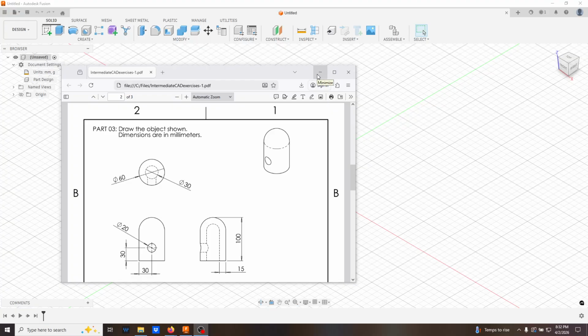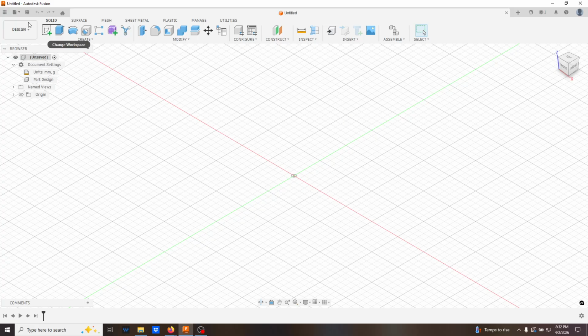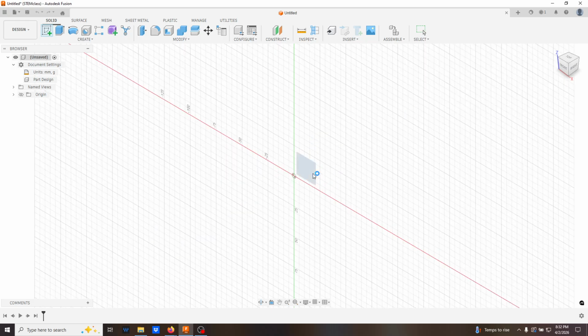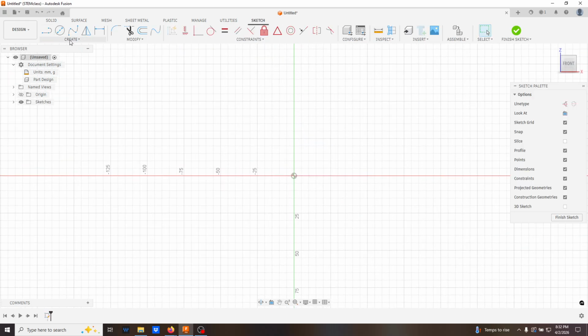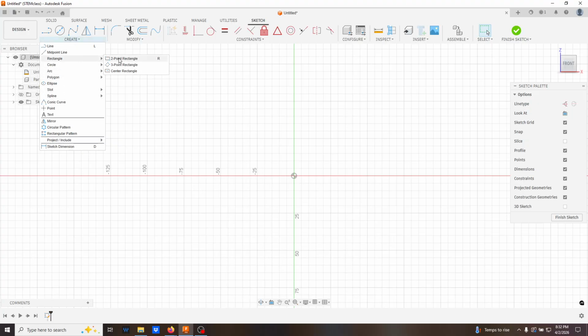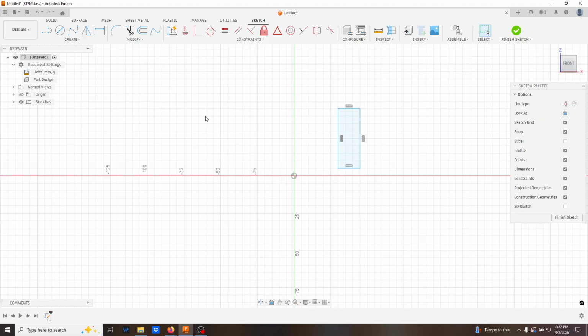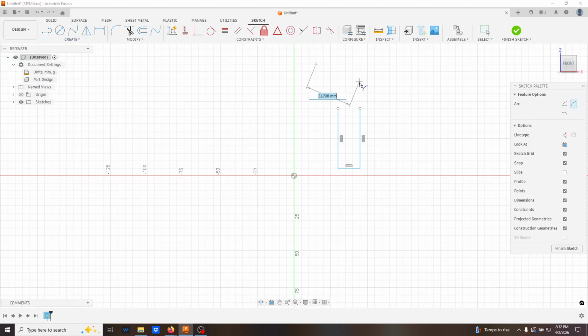Okay, so in the last one, we did a lot of stuff with how we set up different ways to draw that rounded cylinder. So for here, I'm just going to be trying quick and dirty about it. Still highlighting that there's always different ways. I'm going to use a 2-point rectangle because a lot of times I have trouble turning off the auto perpendicular constraints. I'm going to delete this top one here. And so then that way I already get my rounded pieces that I want. And it's again, just keeping in mind how you can build different stuff by stitching different pieces together.